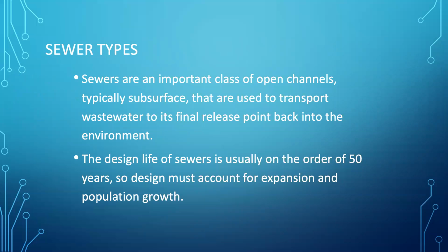So the types of sewers we have are stormwater, which we've examined a little bit already, a sanitary sewer or a separate sanitary sewer, and there's a combined sewer system, which is an old concept, but they're still in use around the world and will likely be for most of your careers, although we wouldn't intentionally be building new combined sewers anymore.